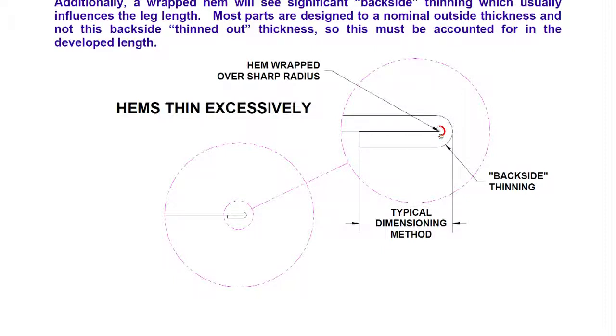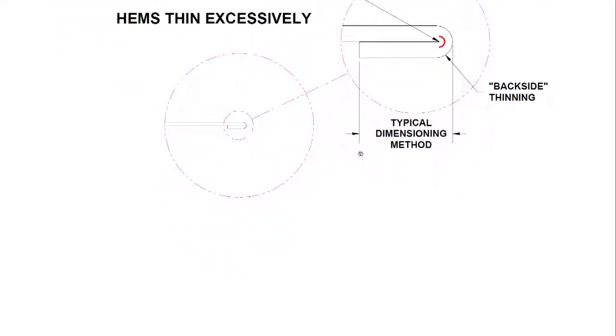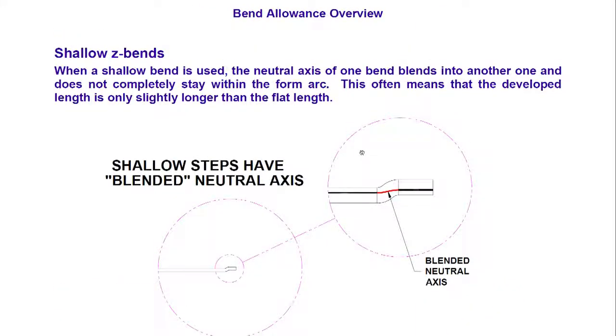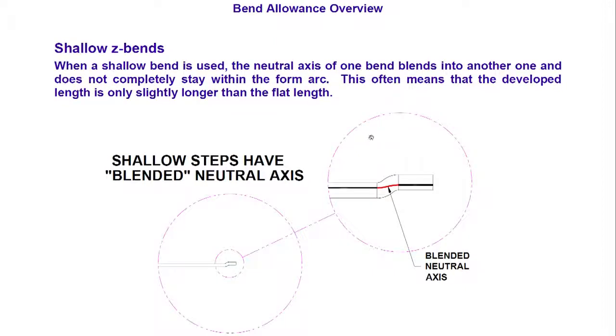Now, imagine you want it a little stronger, probably we would like to have one more limb this side. So, is it alright, can we make it with this? That point is where the designer will take a decision. Probably they will put an L-shaped length here inside separately, and join them together, or have a dimple or something which once it is formed it stays stiff, which will take me to the last but one page,